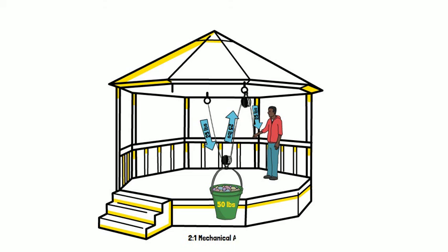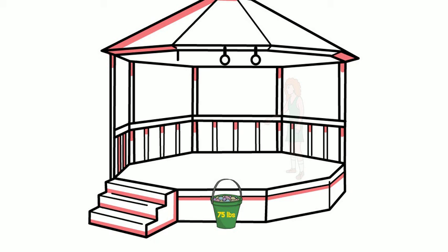By using pulleys, Charles has gained efficiency by reducing friction, and by using a redirect pulley on the second ceiling anchor, Charles has given himself the advantage of gravity. And, thanks to load sharing, the gazebo ceiling is only burdened with 25 pounds on one anchor and 50 on the second. Finally, we'll visit Miranda at the pink gazebo.